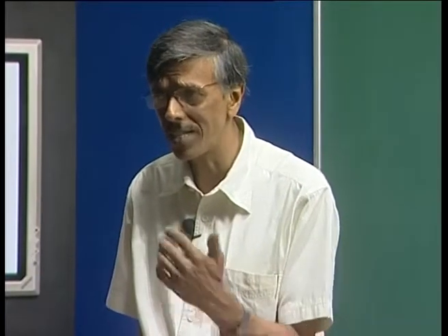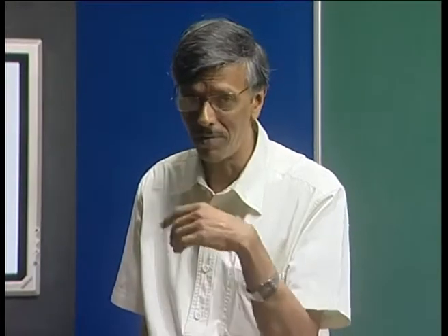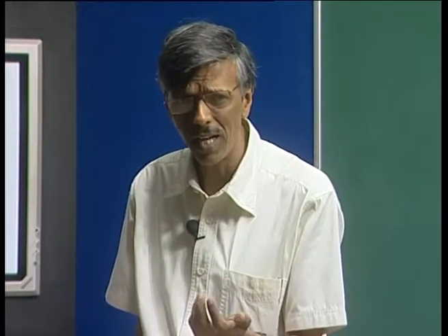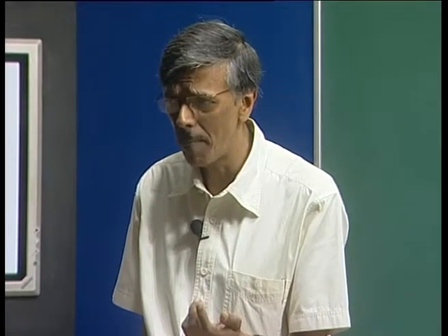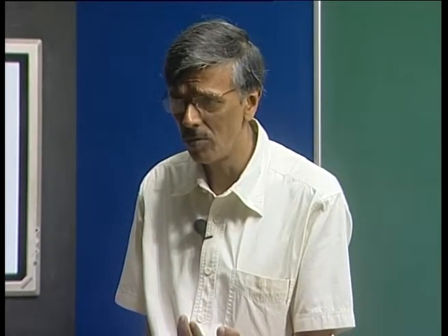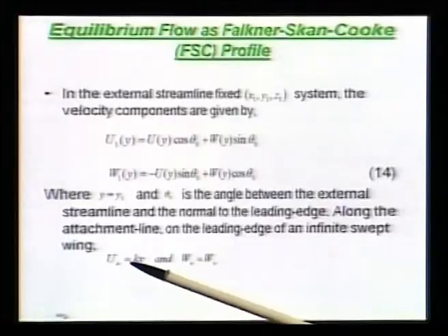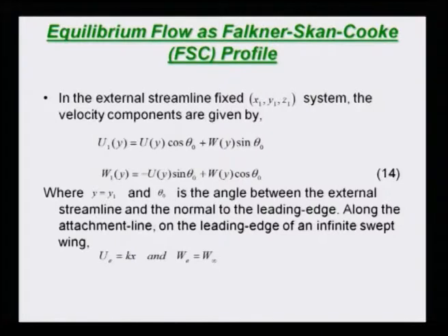This is exactly like what we did for stagnation profile, if you recall. Well, you may have done it in some earlier courses. I did not. Did I do it? I think we did not do it in this course. The stagnation point profile, the Hiemenz flow, we have not done it. But if you look at Hiemenz flow, you would notice that UE would be equal to kx, and V would be some ky with a minus sign.